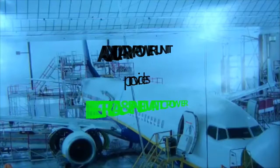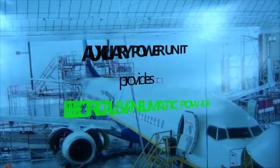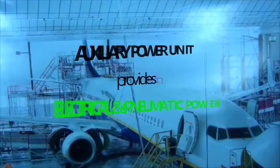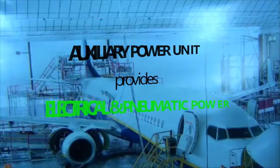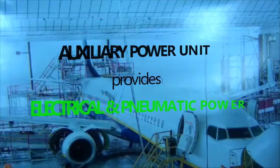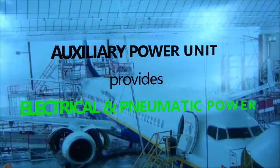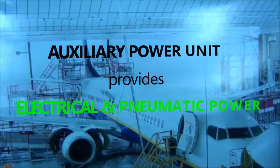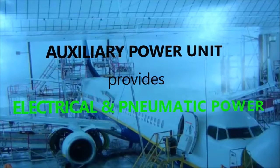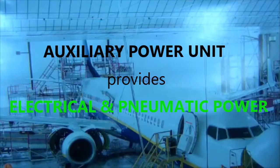Now, as far as your accessory, one of the things, or 2 things, that the APU drives in order to provide the pneumatic and electrical power is the load compressor and also the accessory gearbox. What is it driving? You have shaft power going to those different subsystems I mentioned. On the drive pads, you're going to have your fuel system and oil system. Also you have a cooling fan as part of that as well.